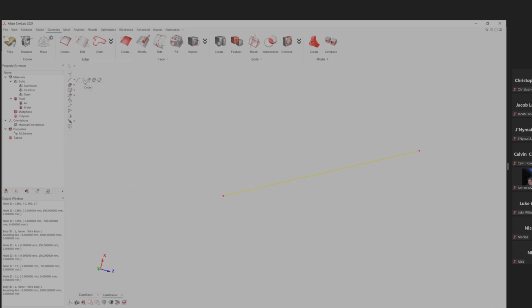Let's say I had a bunch of circles I wanted to select. I could pick a single edge or a circle. It'll identify circles, edge paths, free loops. This is faces. If I wanted to grab the inside of a cylinder or a fillet, I have different selection options. All these are different entity types. This one, I believe, is the default, and this is the body